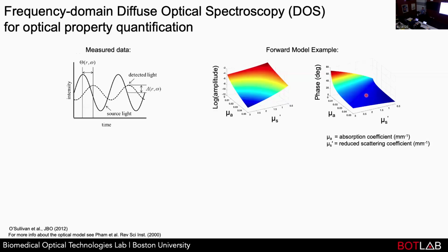We typically use a 3 millimeter active area detector. If you look at the spec sheet from Hamamatsu, it'll tell you can only take measurements up to maybe 50 megahertz, but we use it up to a few hundred megahertz. We're just in the roll-off region where you really lose a lot of sensitivity and we're squeaking out extra performance. So all these things come together.